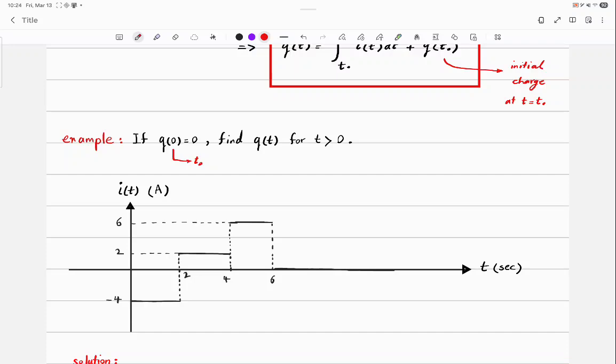What's the value of it? Is it like 5 volts? Is it 3 volts? No. It depends on some other variable in the circuit. For example, it depends on VB. Where is VB exactly? Across the element B. So if you find the voltage across element B, multiplied by 3, it will give you the voltage across the voltage source. That's why we call it dependent. Did that make sense? Okay.